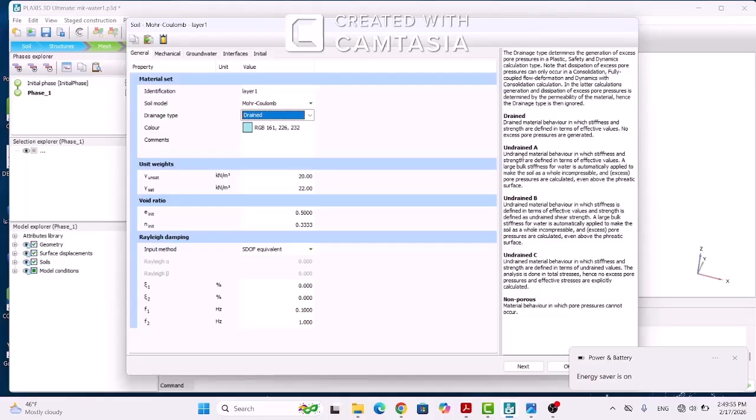So in consolidation mode, we need to know the situation of the model during the time, because at the first of consolidation, the excess pore water pressure is high, so the effective stress is low, but during the time, excess pore water pressure will decrease, and effective stress will increase.